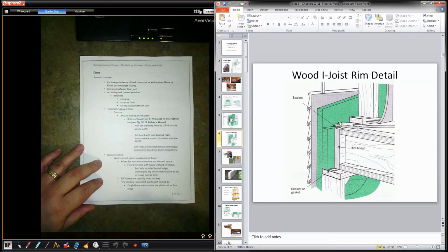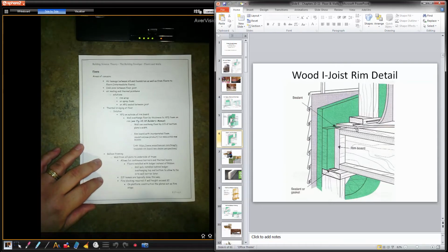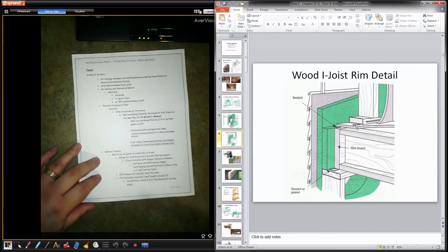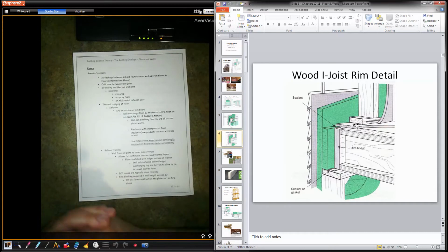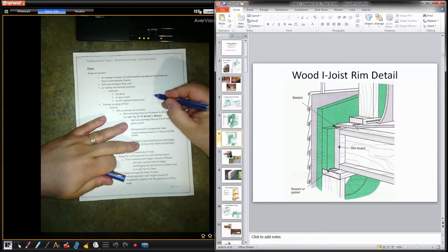Some people would say that would be weak because this would want to fall. So you're allowed to have the floor hang out 1/3. It has to bear 2/3. So that 1/3, 2/3 rule is something that we talk about quite a bit in construction. So how much wood is left at the top of a rafter when you cut a bird's mouth? 2/3 of the material. Right? So I'll just do a little sketch here. So we see that a lot, 1/3, 2/3.